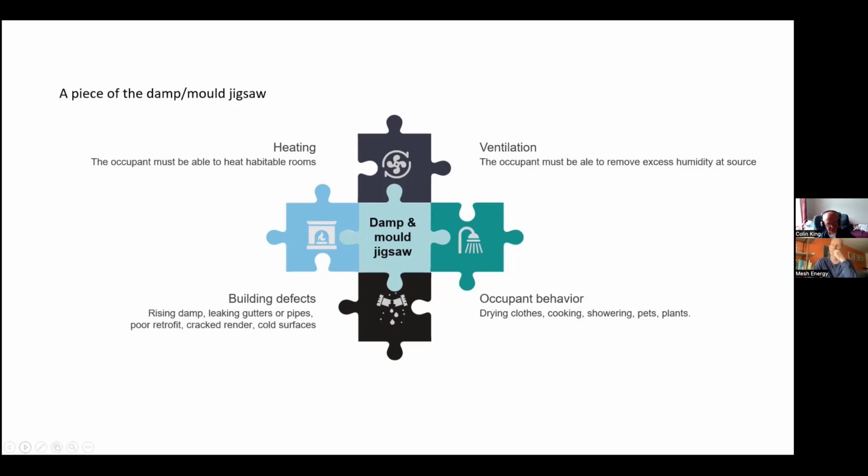And historically, if you look at damp and mould, kitchens and bathrooms which have ventilation are very rarely the locations where damp and mould is formed. It's in circulation spaces and underheated, underused rooms of the house. So most houses you will go into, we've all got one, I've got one, the back bedroom on the north facing wall, which I dump all my stuff in. I very rarely heat it very high, and so it suffers from mould.